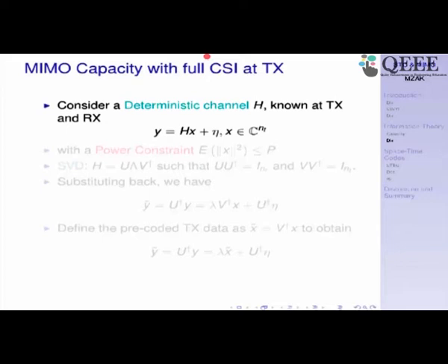From here on, I'll go to a third case. See, in the previous two cases, I have assumed that the channel H is only known at the receiver, and it is not known at the transmitter. That's why in the derivation, when we took Q, we actually substituted it as identity of NT times gamma by NT, because we don't know the channel at the transmitter, so the best policy is to transmit equal power on all the NT transmit antennas. That was the derivation.